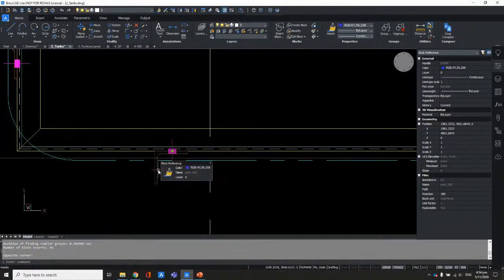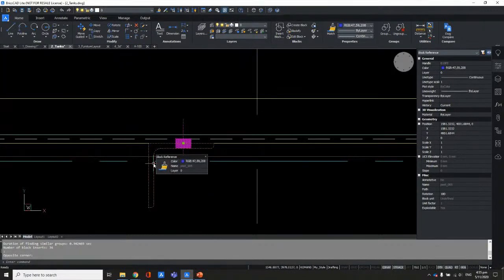It studies your whole drawing and it will detect the same type of geometry that you selected. So this type of form and geometry and the way the lines are drawn, and select those and turn those all into a block. So if I hover here now, our rollover tip is correctly saying that now it's a block. Even the properties panel is telling me it's a block.